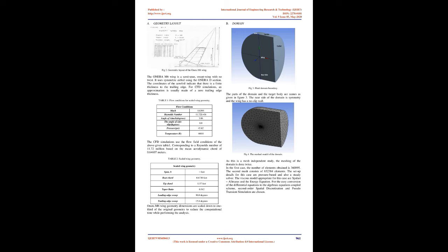According to the Federal Aviation Administration, FAA, the standard crosswind condition which any commercial aircraft should be able to handle is 30 knots. In this experiment we are considering both 30 knots, which is a standard crosswind velocity, and 50 knots, which is a severe crosswind velocity, to check the effects of the main rudder along with the Winglet-Rudder on the net force to ensure a safe landing.